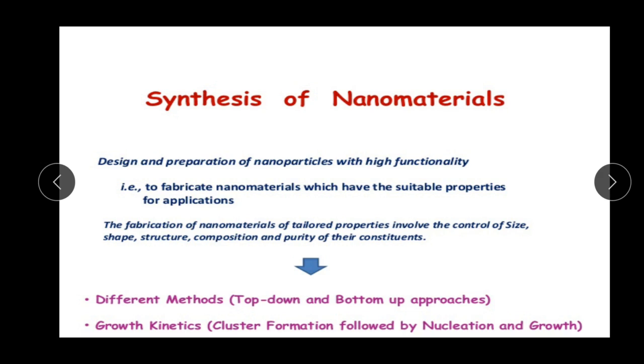The synthesis of nanomaterials is the design and preparation of nanoparticles with high functionality, that is, to fabricate nanomaterials which have suitable properties for applications. The fabrication of nanomaterials with tailored properties involves the control of size, shape, structure, composition and purity of their constituents. There are two methods by which we are going to fabricate nanoparticles: top down and bottom up approaches, and also we will use growth kinetics, cluster formation followed by nucleation and growth.